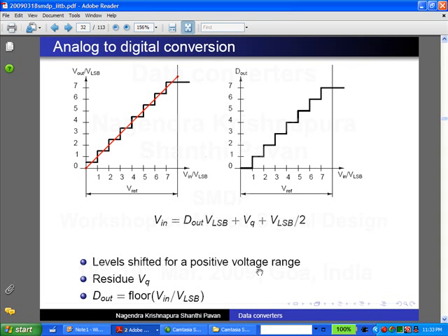So if you want to simulate an A to D, but not at the circuit level, you have not yet designed the circuit. You want to see the characteristic or whatever I said about distribution of quantization error and so on. All this you should simulate and verify because that's the only way it will actually stick on, right? Whatever I say, it could be false also. So you should verify it yourself. And the easy way to do it is you use one of these rounding functions in MATLAB that will give you quantization.